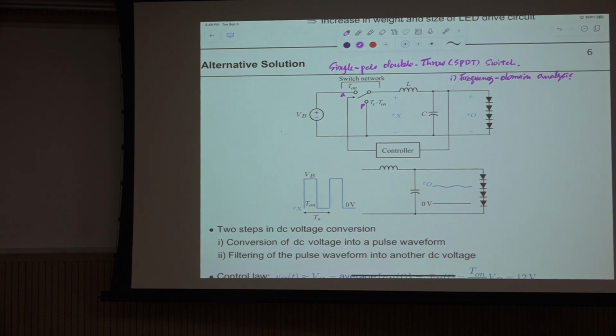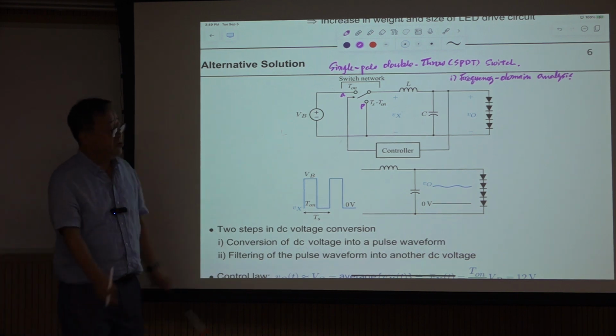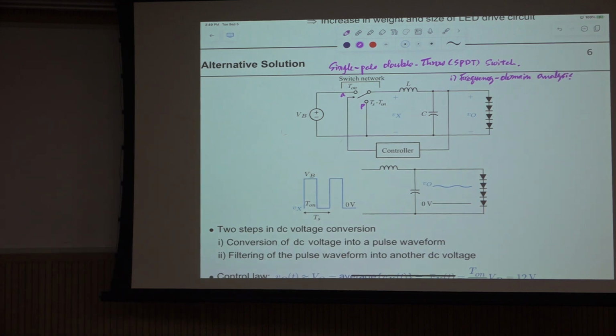So this is a periodic waveform. So the Fourier series of this contains the DC component, a0, and the fundamental component and second harmonic, third harmonic, and so on. Okay, so from omega s to 2 omega s, there is a distance here, and omega s is the switching frequency, 2 pi divided by Ts. Ts is the switching period.